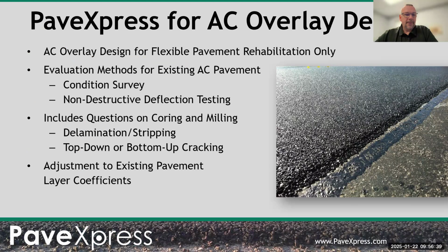Let's see. I've got one asking, should you include sub-base material and strength in your layer design? And if so, how deep should you cut off that layer of sub-base material? Yeah, you can add a sub base too. A lot of it depends on what your subgrade material is. Say, for example, if we're on a poor subgrade material, you might want to put a sand sub base and an aggregate base underneath that.